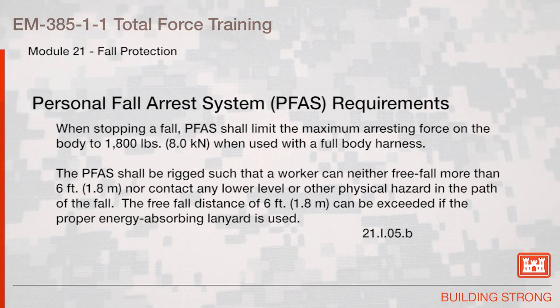When designing new personal fall arrest systems, the qualified person shall attempt to minimize fall distances, including free fall distances and arrest forces. If it is necessary to increase free fall distances and arrest forces in order to accommodate existing and new structures or provide mobility to end users, only the qualified person can make this determination, and the maximum arresting force shall be kept below 1,800 pounds.